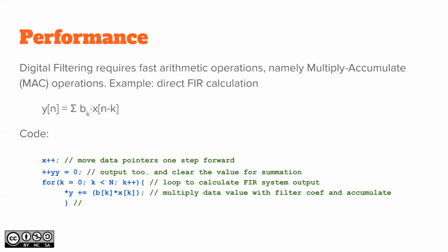If you have integer numbers, you need to make sure that the integer variables holding the data have a long enough word length that you can, for example, multiply two 8-bit signed values. That takes 16 bits to save the whole value. Or you can just multiply and cut the remainder, since that's just decimals. Well, okay, not quite, but anyways.